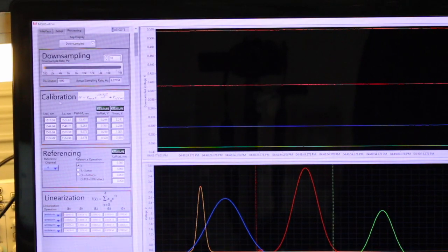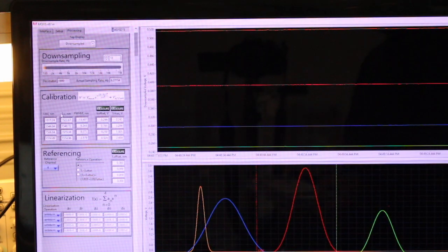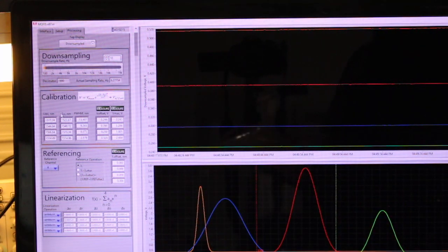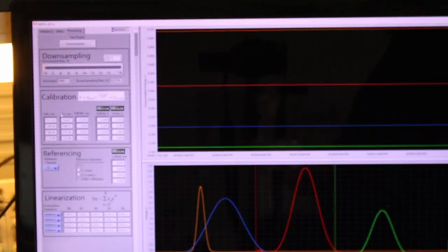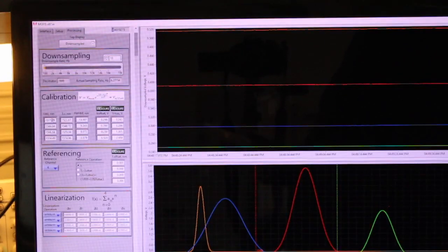In the first column of the calibration, it tells us that we should enter the wavelength of the fiber Bragg grating sensor. I do have a fiber Bragg grating sensor array, and I want to compare that this array matches the wavelength parameters there. So on the first channel, the wavelength that I have is 1517.241, and this kind of matches that number.